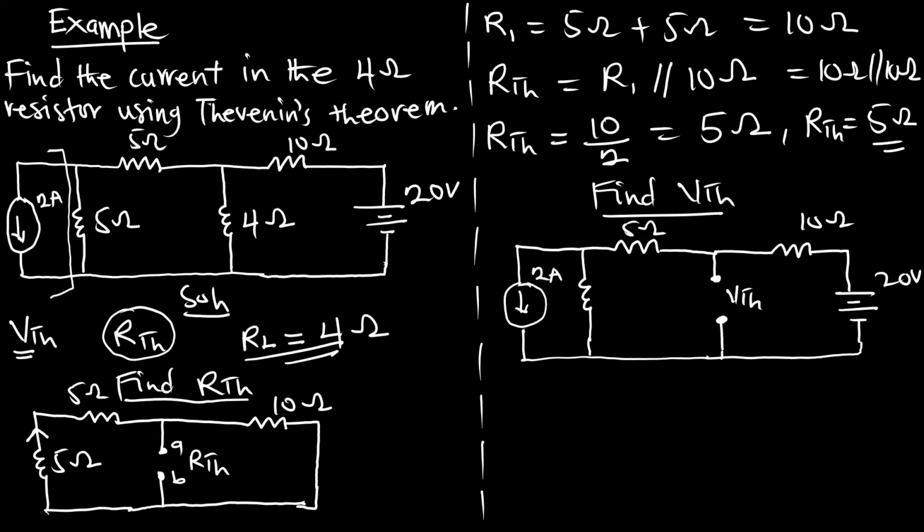If we are going to assign current, now this whole part forms loop 1, and let's call this loop 2. If this part is going to bring current through the circuit, we are going to get our current, say I. This current I is the same current flowing through this 5, because if we assume it's going to split here, it is open, so no current is going to flow. So all the current is now flowing through the 5 ohm resistor. So no current through this part.